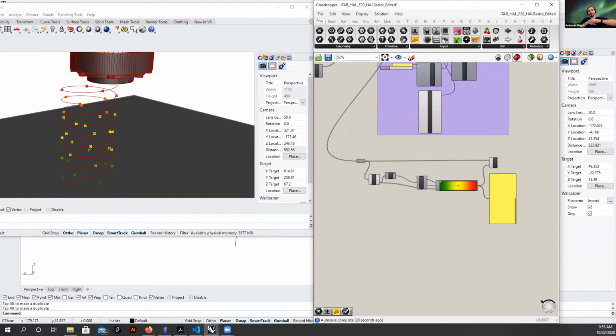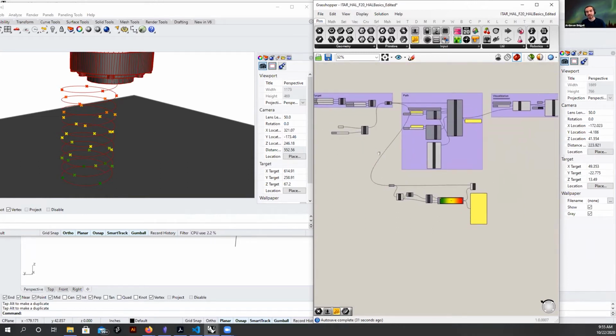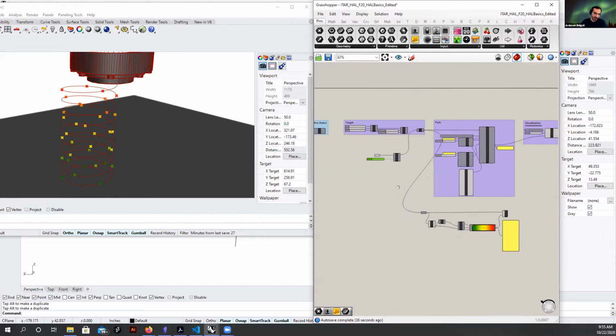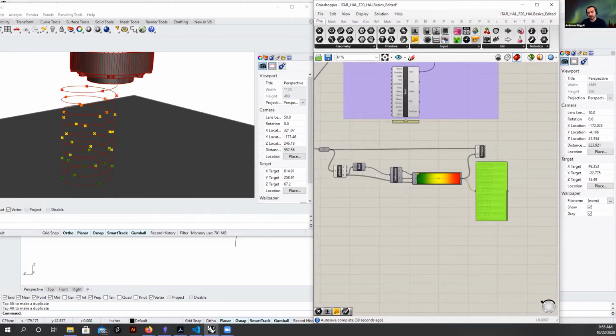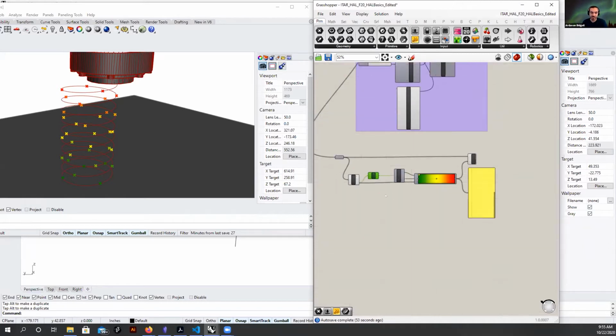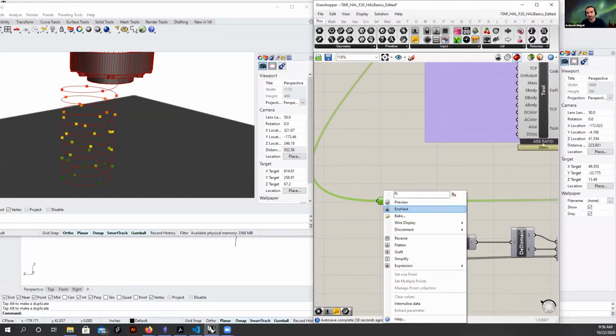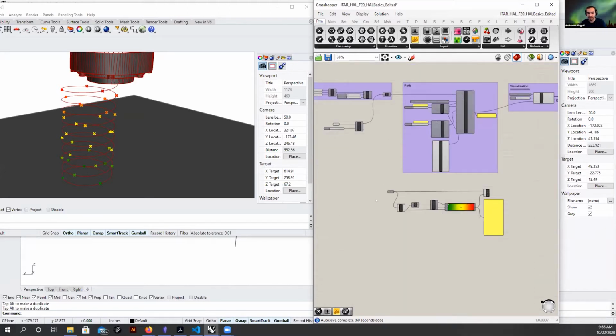So they're overlapping. Grasshopper has this problem a lot because when you're making a new component or you do something, it just duplicates objects on top of each other. And it prevents you from seeing them one after each other. That's a serious problem. So it's a good idea to keep this habit of hiding whatever you're not actively using, so it's not going to interfere with your visual communication. Or you can use the options on the top, that barrel that has half of it green and the other half somehow faded. That's going to help you to just see what you are selecting.